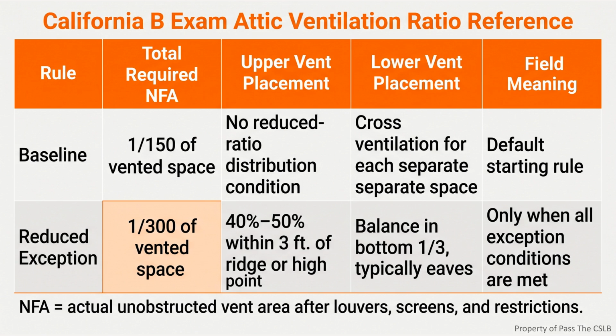That is the central field decision in this lesson. I do not inspect vents as isolated products. I inspect the path from intake to exhaust. The most important point is the part that often disappears behind insulation and drywall, which is the clear roof framing airspace. Imagine a contractor who counts every soffit vent and confirms the ridge vent length, but never looks into the eave bays after insulation is installed.